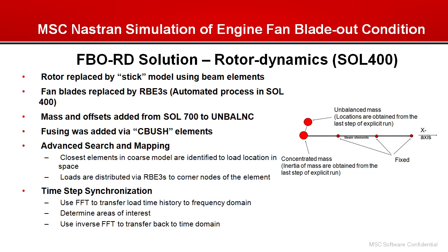In this example, the sectional property of the stick model was computed based on the hollow shaft rotor of the explicit model. The stick models basically can be obtained using Guyan reduction or the classical lumped mass technique. The figure on the right is a representative shaft model in the rotor dynamics analysis using beams.